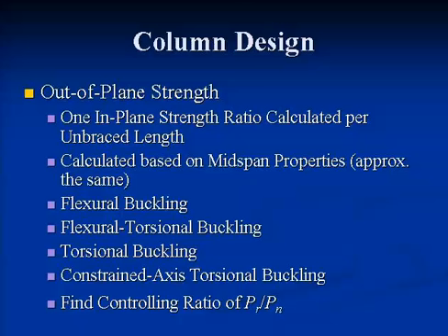And this is something else I think we lifted from Timoshenko. Basically it's a torsional buckling formulation that's based on the assumption that it's buckling about this line of more or less constant braces. And it gives you a pretty good answer, which is somewhere in between.